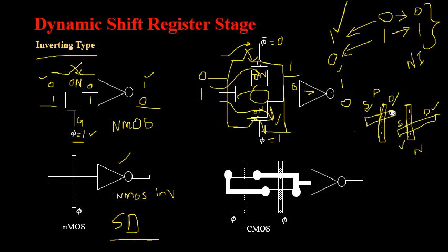So it is a different layer because this is a diffusion layer of P type that has to get connected with an N type of diffusion now. So this is a metal layer what I am using and I have to join the drain terminal. Once again I am making use of a contact cut in order to differentiate between the two layers, because there are two layers and they have to be connected together. So it is possible only by making use of a contact.